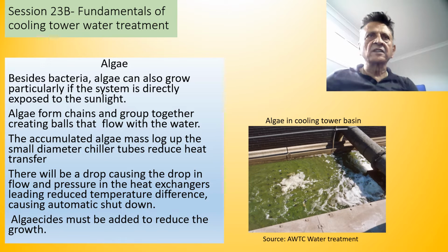Algae is particularly supported by sunlight, and if the cooling towers are situated in direct sunlight with timber slats being constantly wet, then these slats will grow the algae.